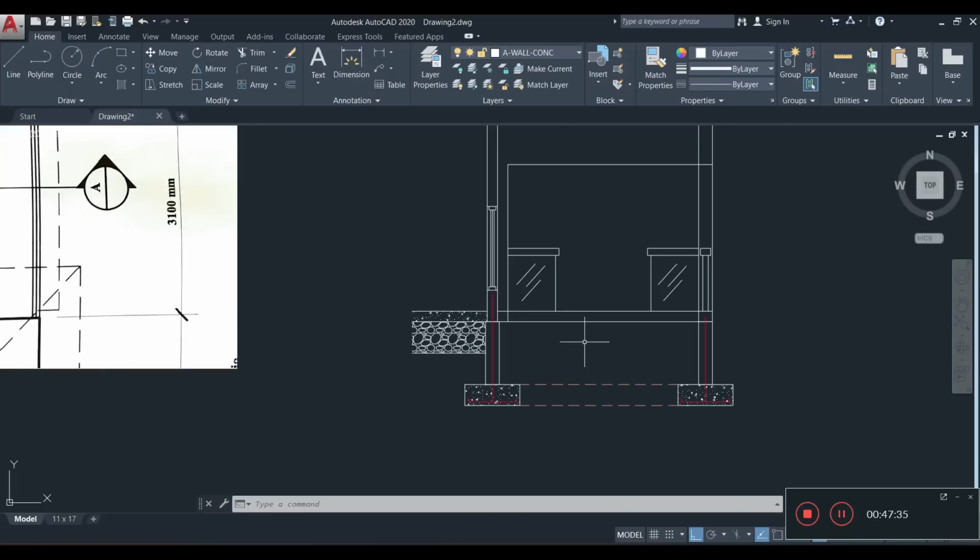Now, people will have different variations of how they do their suspended slab. How I do it, and this is how it is done in America when it comes to suspending floor slabs and all that, they have some stuff that they call hangers. They're made from galvanized metal, and they're pretty much like shears that you nail onto wood or onto a wall, and then you simply rest the 2x4 or whatever board inside of it. So what will that look like here?